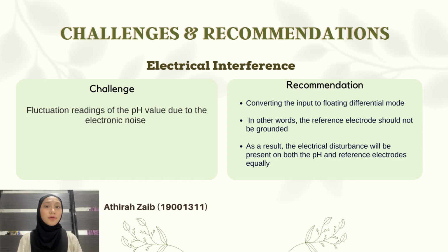One way to overcome this problem is that the reference electrode should not be grounded. As a result, the electrical disturbance will be present on both the pH and reference electrodes equally. Therefore, it becomes a common mode signal and can be dismissed by the operational amplifier.